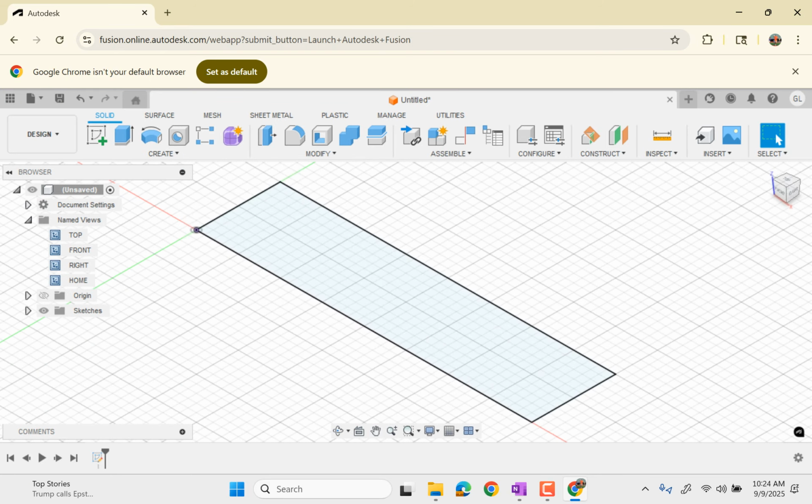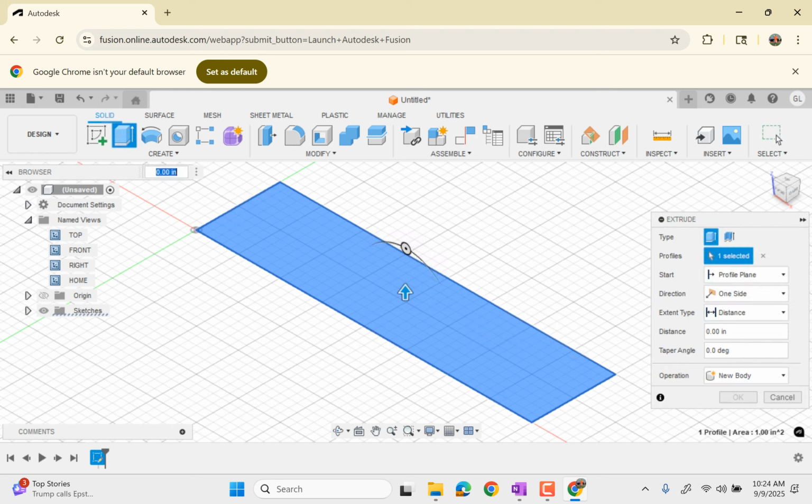so that we can see it in a sort of three-dimensional shape. We can see all the axes. And now I'm going to extrude this shape. So to extrude it, I'll highlight the whole thing, go to extrude. It suggests this direction. That works fine for me. And I want to make this distance 0.4.